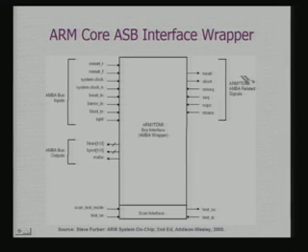Here the signals come from the ARM7TDMI, the AMBA-related signals that are directly available, and these are interfaced onto the AMBA bus. The HREADY signal that we discussed in the case of the AHB bus is BWAIT in the ASB bus, because the definition is slightly different, and it is equivalent to nWAIT on the chip itself.